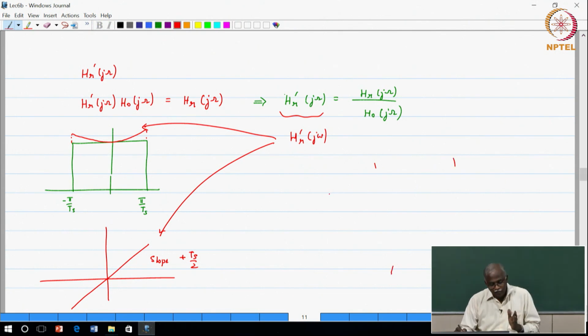Okay. Now, designing an analog filter with these sort of compensations may be difficult. So, that is where once again DSP and multirate DSP can come, because you can do the pre-compensation. Basically, you can compensate the input signal x of n before it goes into this staircase approximation. So, the compensation is actually done before the distortion occurs, and you take care of it in the discrete time domain itself.